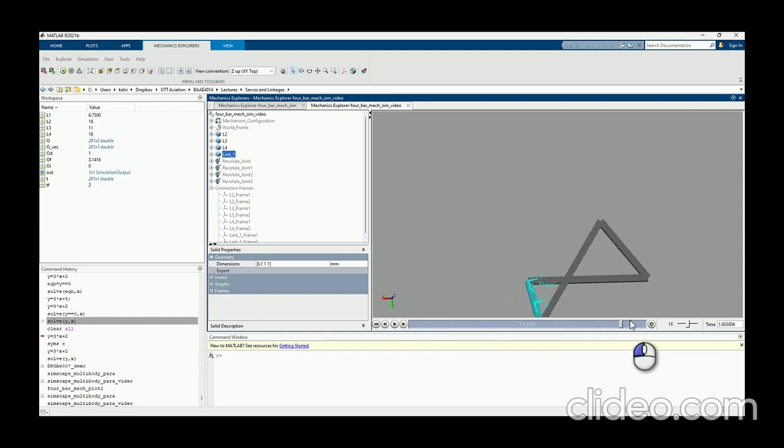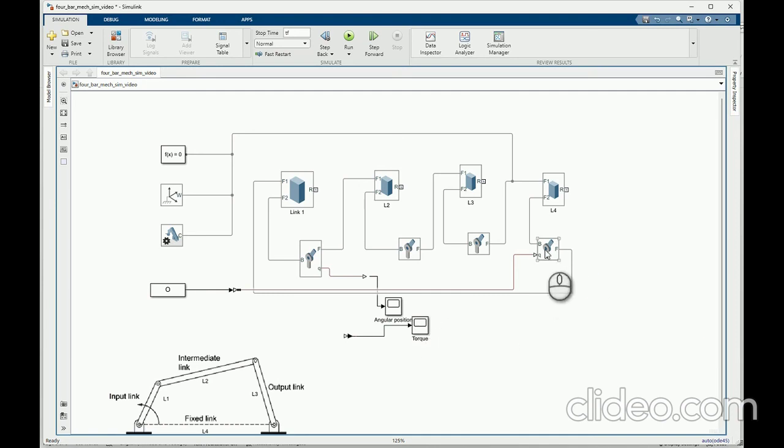Now that we have everything, we could manipulate the values to get the motion we want. The reason why we are doing all this is that we are able to obtain that actuation torque, so that we will know if the motor is capable of providing the motion that we want.